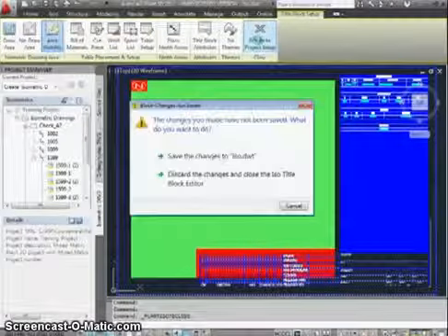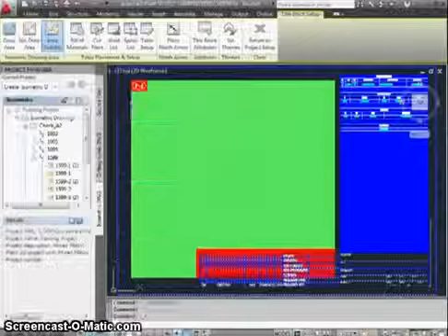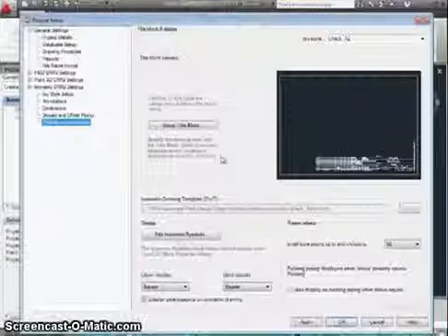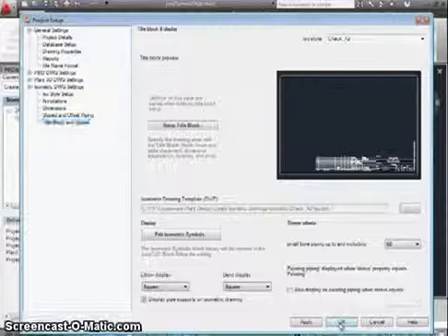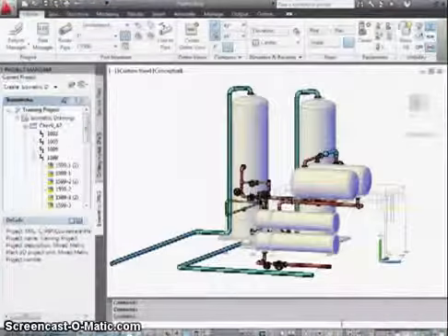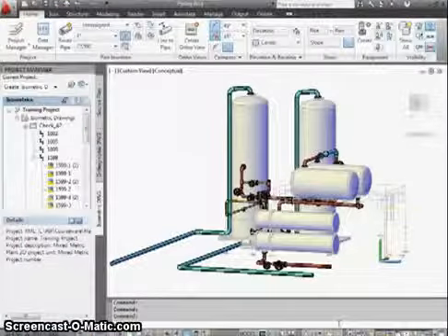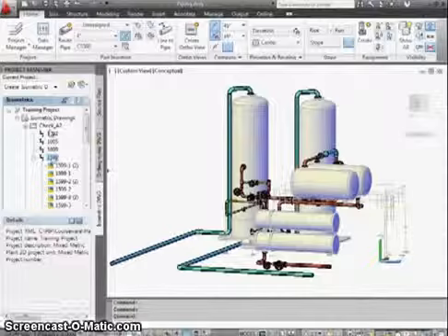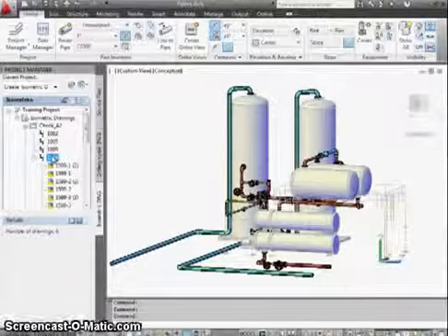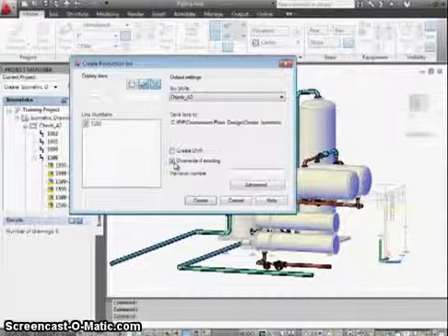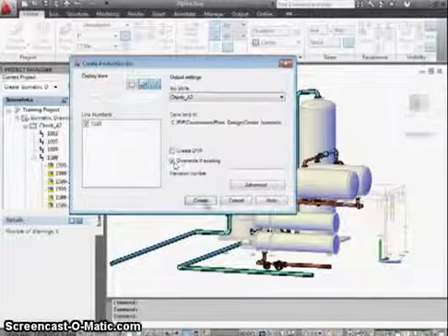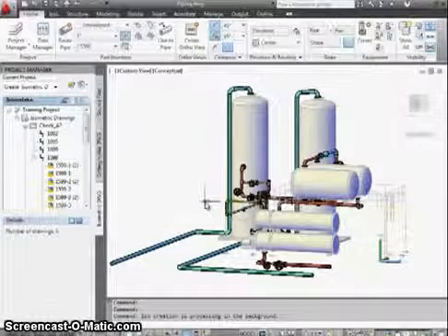Okay, so let's close the title block setup and save our changes. Then we can close Project Setup. And then back in the Isometric tab of Project Manager, we'll select line 1599. Let's create a production ISO, and this time we'll overwrite the existing DWGs.